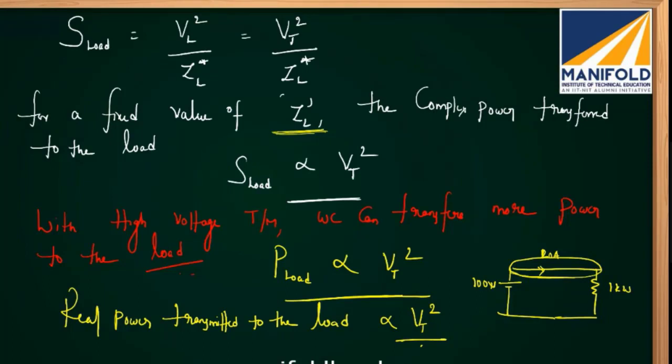When we purchase aluminum, by default we get a larger cross section area for the conductor. With the larger size of the conductor, one disadvantage exists that we are using more conductor material, but since its density is less, the weight of the conductor will be less. However, to carry the same current, the overall size increases.